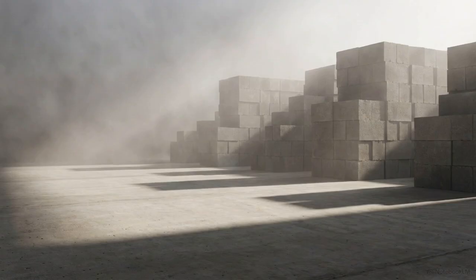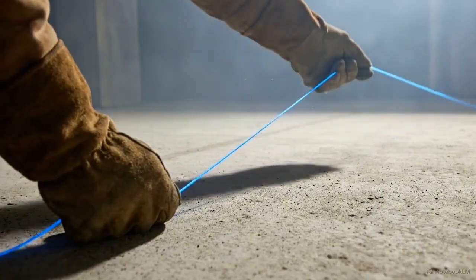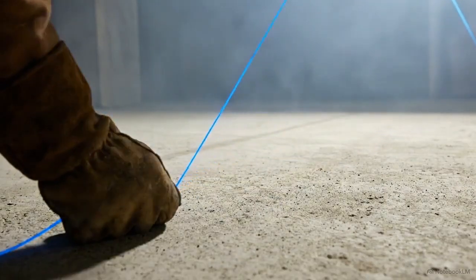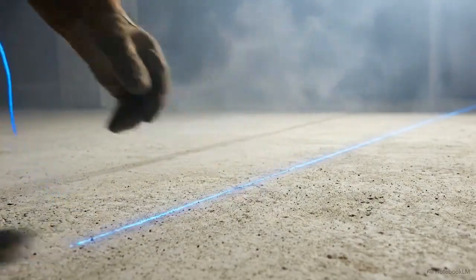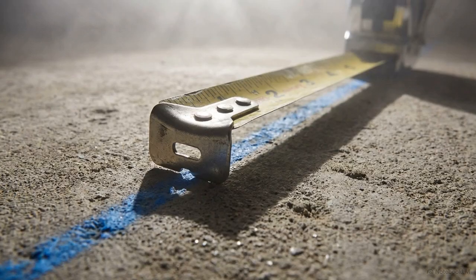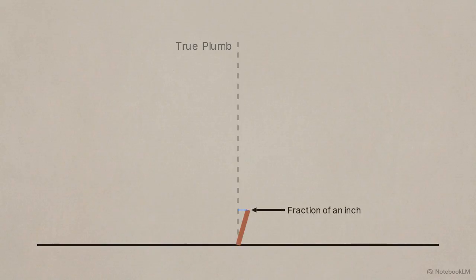The physical construction process begins on the ground. Builders start by marking out the exact wall position, often by snapping a chalk line across the foundation slab to establish a perfectly straight base. Skipping this measurement or rushing the foundation prep locks in structural errors immediately. A base that is off by just a fraction of an inch guarantees a crooked wall that cannot be corrected